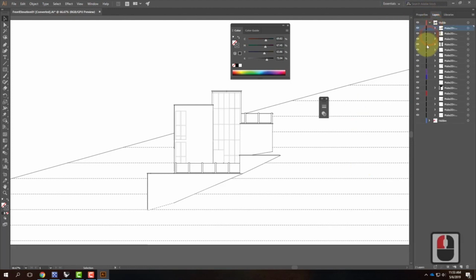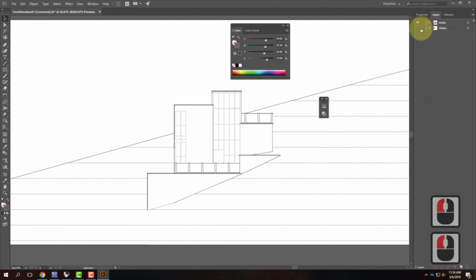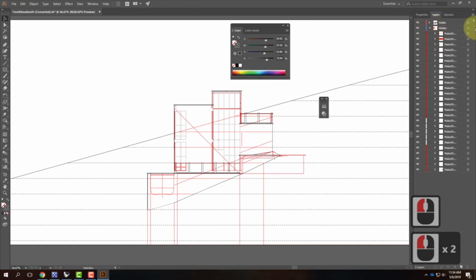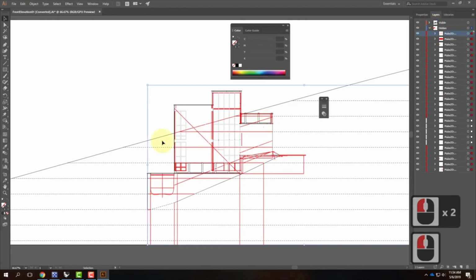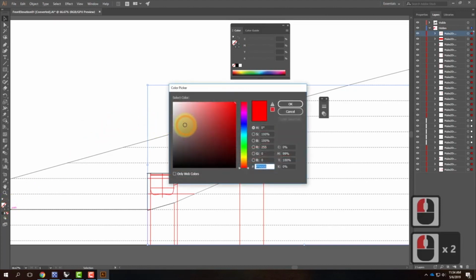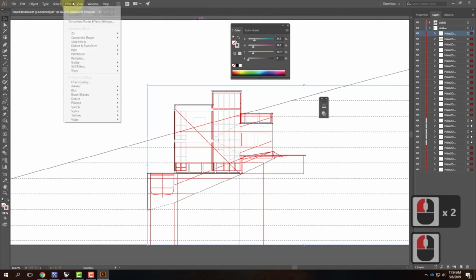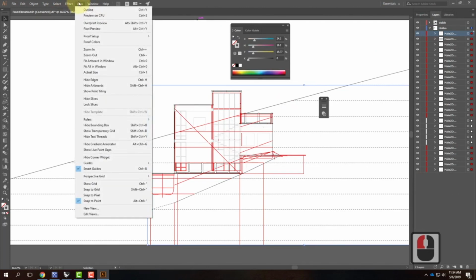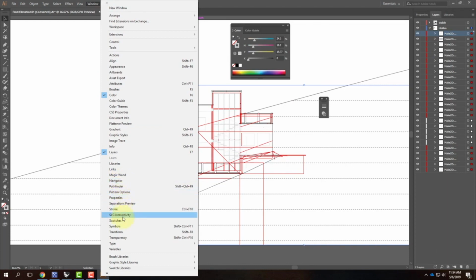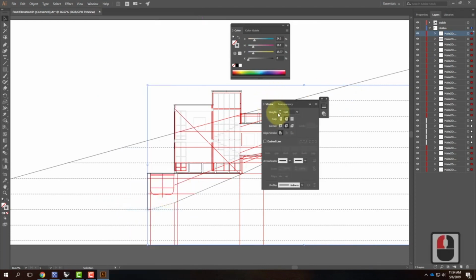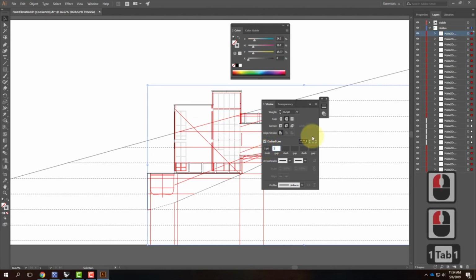When it comes to the hidden lines, those were all the visible lines, I could take all the hidden lines. I'm just going to select all of them right now. There they all are. I'm going to make all of them a faint gray color, something like that. I'll make all of them dashed. So let me go into my Window and then Stroke again. There it is. I'm going to make them all maybe 0.2. I'm going to make them all dashed, and instead of 6, I'm going to make that much finer. We'll go 1 by 1. So there are little itty-bitty lines there.